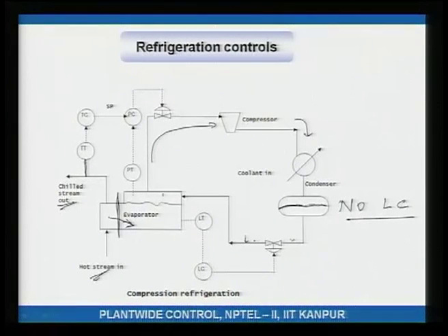Of course, there are those leaks, but those leaks are taken care of after some years of operation by just putting in a little more, just filling up the gas. And how is that indicated? This level over several months or maybe a year or 2 years of operation will continuously go down. So, once this level has gone down from say 60% to about 30%, you may decide, well, slowly but surely we have lost enough refrigerant, now we need to charge more refrigerant.